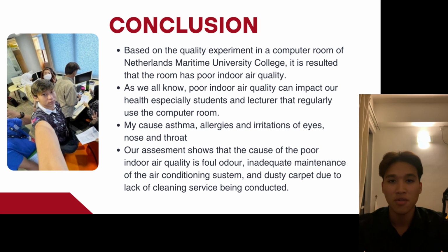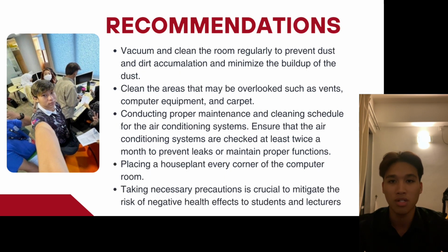Our assessment showed that the causes of the poor indoor air quality are foul odor, inadequate maintenance of the air conditioning system, and dusty carpet due to lack of cleaning service. We have proposed some recommendations to improve the indoor air quality of the computer room, which are vacuuming and cleaning the room regularly to prevent dust and dirt accumulation, and cleaning the areas that may be overlooked such as vents, computer equipment, and carpet.